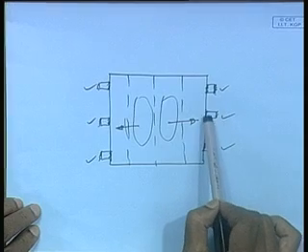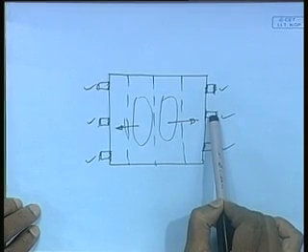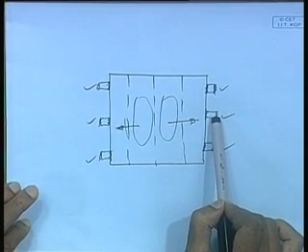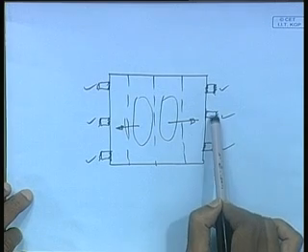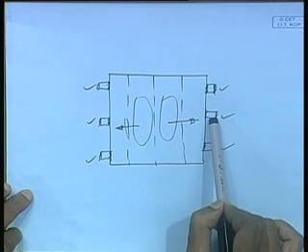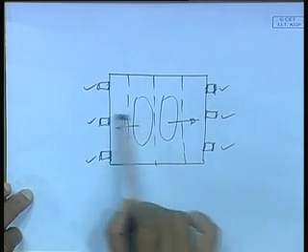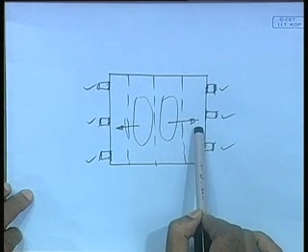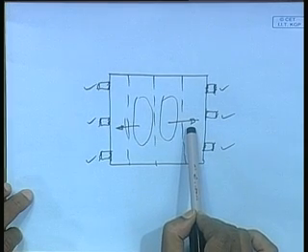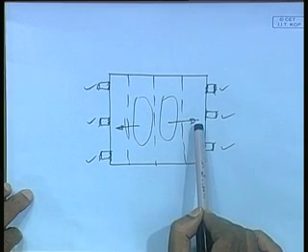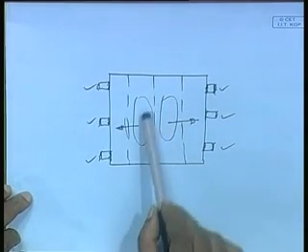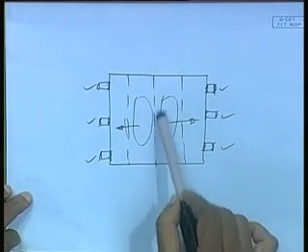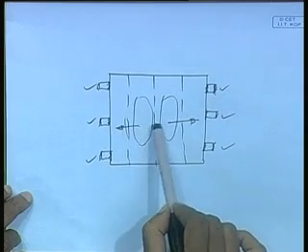Prior to welding, the lugs are heated up. They are heated up to an elevated temperature and then welded. The result is, the moment they are getting cooled down, they are contracting and putting the plate in tension. It's a very simple but quite effective method, and very easy to implement. So, thereby one can do away with the problems of buckling distortions because of welding of the stiffeners.